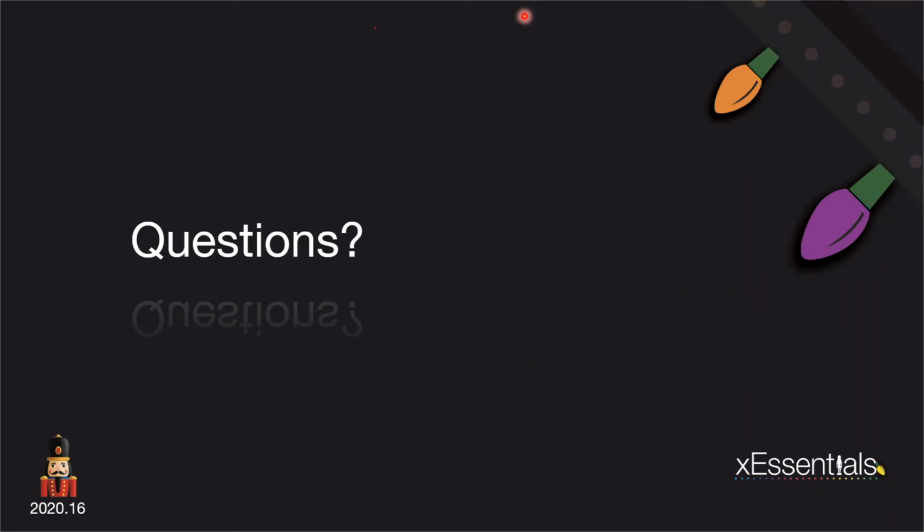Okay, so if there are any questions for Mark, feel free to unmute yourself and ask away. I do see the question in the Zoom group chat that says, what milliamp minimum? I apologize, I'll go back to my slide about math. I know off the top of my head, a Raspberry Pi Zero W is 150 milliamps. So take a power supply and take the rating and divide it by the 150 milliamps plus how many pixels you're going to be running, and you can roughly get how many hours. So I do kind of know what the rough math is, but I don't know the exact answer.